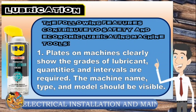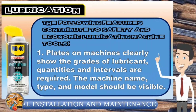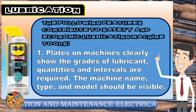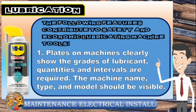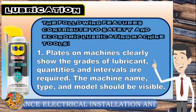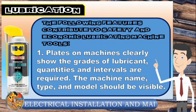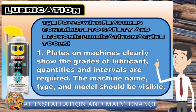Now, let's talk about the lubrication. The following features contribute to safety and economic lubricating of machine tools. We have number 1. Plate on machine clearly shows the grade of lubricant, quantities and interval required. The machine name, type, and model should be visible.